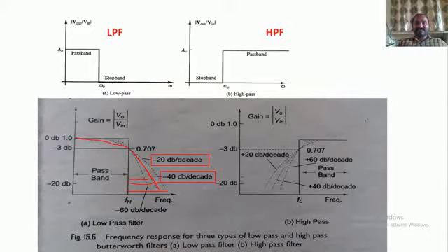No sir, I am not satisfied with this one. Then I am going to increase the order of the low pass filter. That is nothing but the third order of the low pass filter. You can increase further, to fourth order, fifth order, like that. But if you keep on increasing the order of the filter, there is more complexity in the circuit diagram, and at the same time, even though you are trying to increase the order of the system, you will never get the ideal characteristics, because the components are not giving what we are expecting because of their internal properties and characteristics.